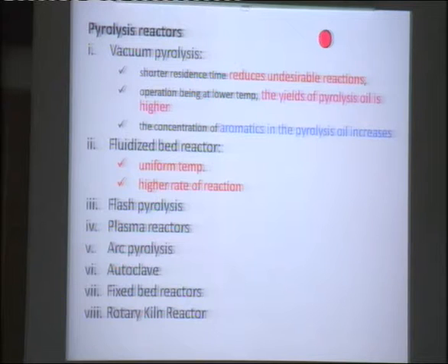Next. Here we have shown that with catalyst and without catalyst, okay, how much gas, liquid and residue you are getting. You see, you are getting at 400 degrees centigrade using the silica alumina catalyst, 93% liquid, but without that you have got only 0% liquid. Gas is very small. Okay.